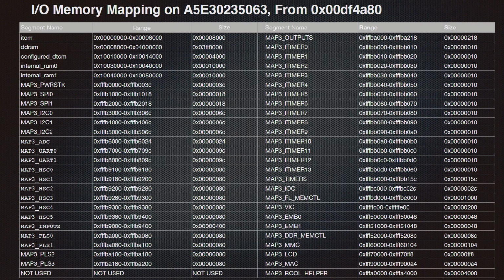Another thing that has not been documented before is also interesting, in the sense that we can talk to hardware directly, which is MMIO, memory mapped I/O, and we have some of those ranges here. We can see that different pieces of functionality and hardware are supported. For example, SPI flash is supported, of course, so we can talk to SPI directly. Or we have a bunch of timers, and we have an analog to digital controller and so on. So if we wanted to create, for example, a driver for this, we could use those ranges to implement it.